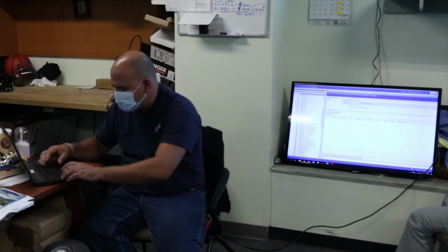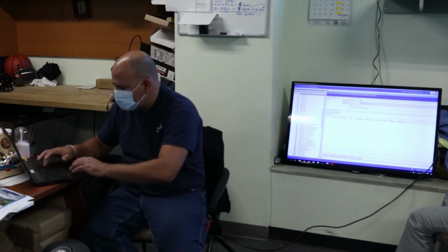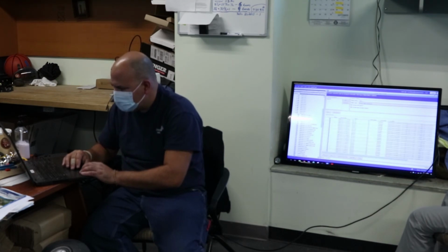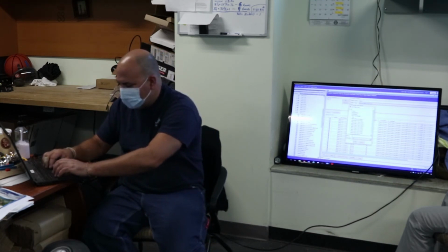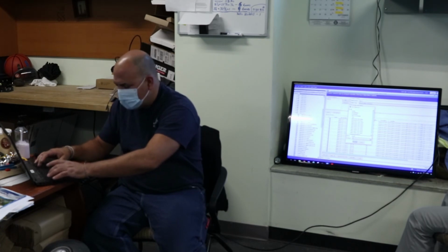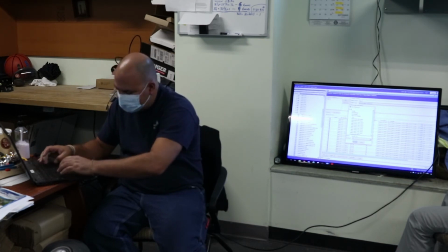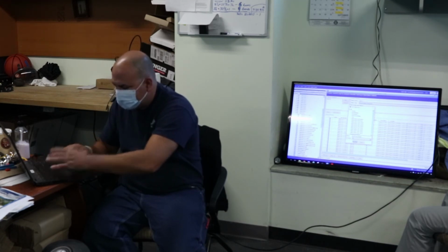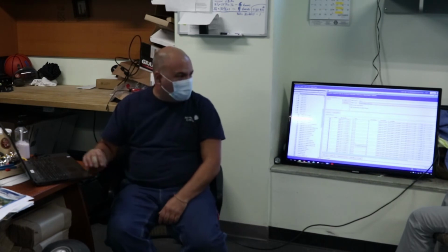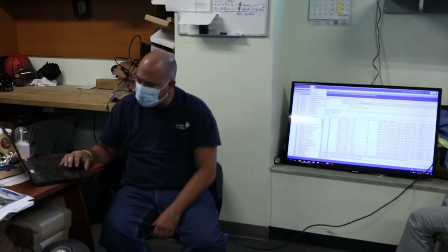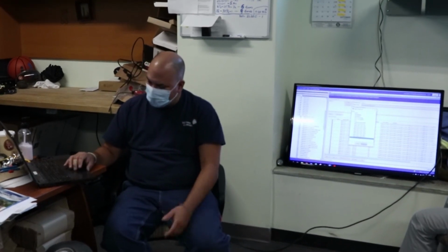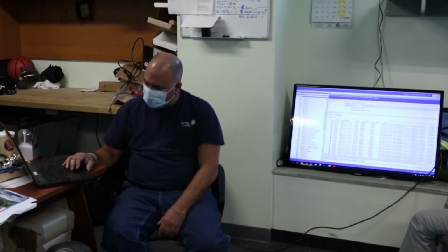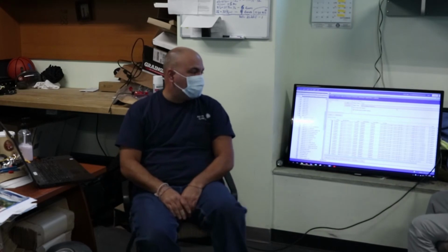So if I want to do the search, and now if I want to save the object list, I can save this, and I can give it a name, AHU1 VAV damper. And I could save it like that. And now every time, so now you go to the query and you go to open object list. And you'll see we have a reheat for AHU4 saved. I can see the position of all the heating valves in AHU4. So it's a good tool.